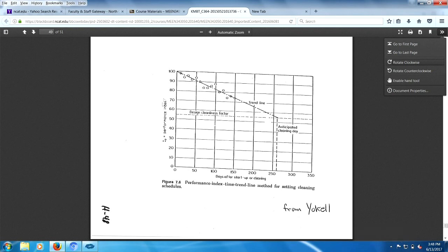So you plot the performance index, the overall heat transfer coefficient, with time. As it continues to get dirtier, it'll drop. That means you should have online capability of calculating your heat transfer coefficient. Measure the temperatures in and out, and you know the area of the heat transfer. The temperatures in and out give you how much heat was transferred, and the log mean temperature difference is there in the temperatures, so it's an elementary calculation of the overall heat transfer coefficient.